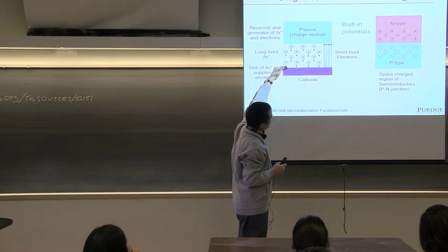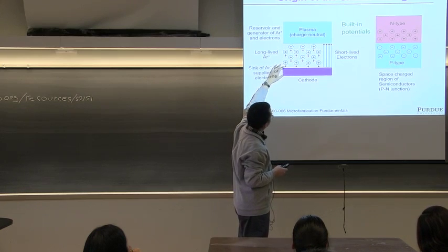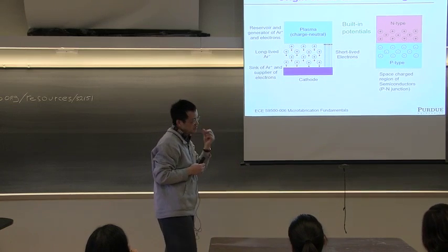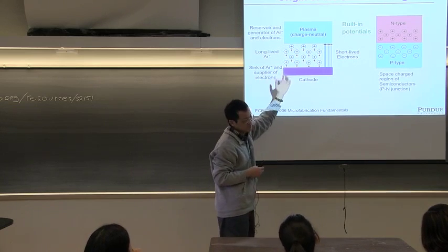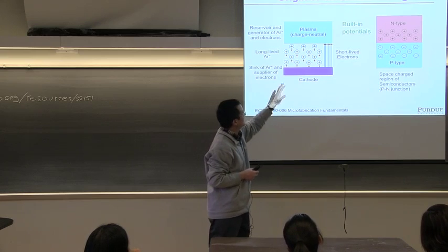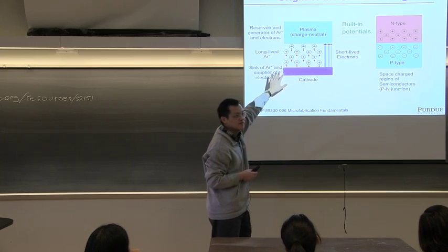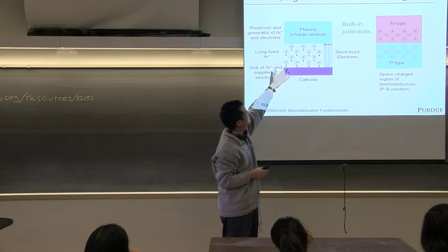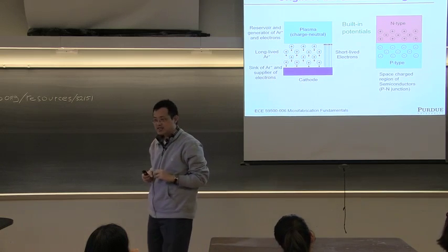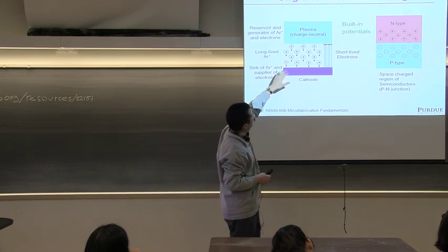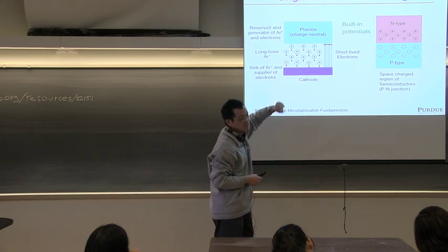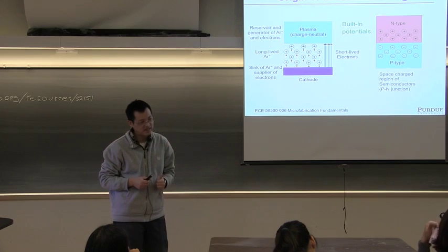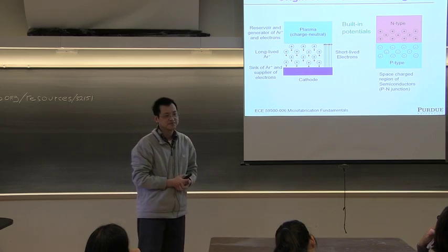But towards the edge, where the electrodes are, there's a region where you just can't balance the charges, and this is a region where you have a much higher concentration of positively charged ions. If we apply Gauss's law, if you have positively charged ions in it, it will build up a potential, and this is where the sheath potential is. Once the positive ion gets into it, it gets accelerated and strikes the substrate with high velocity and directionality. Both are very important. All right.